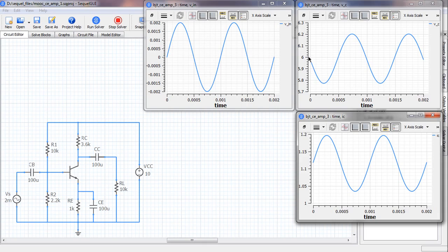When this increases, that decreases, and so on. Its base value or the DC value is indeed 6 volts, very close. And the peak to peak variation here, let's see how much that is. This one division is 0.1 volt, so we have 0.1, 0.1, 0.1, 0.1, and maybe 0.02 or something like that. So it's 0.42 or 0.43, and we expect 0.45, so it's reasonably close.